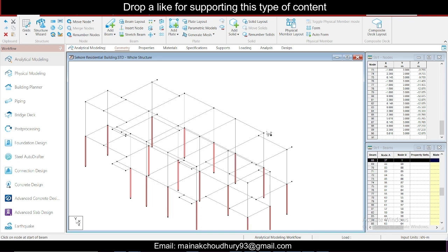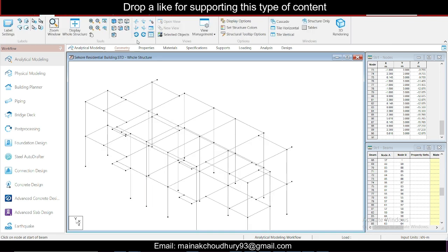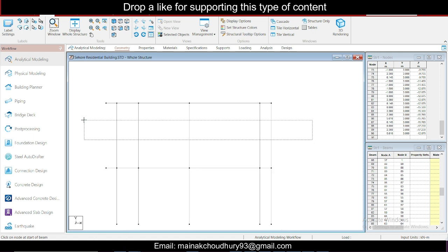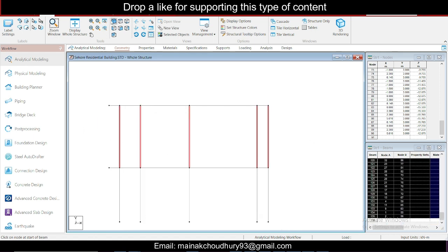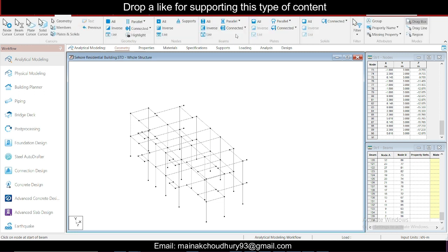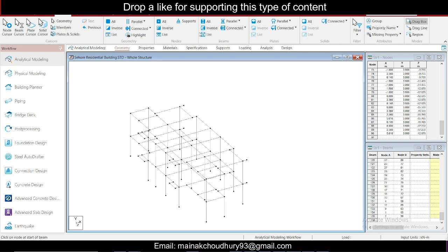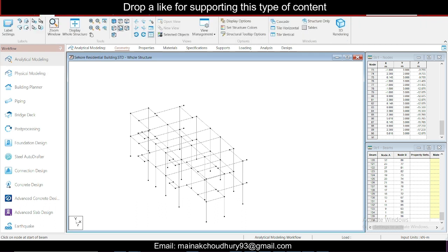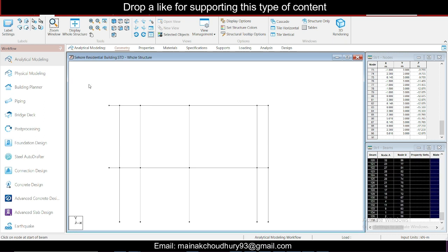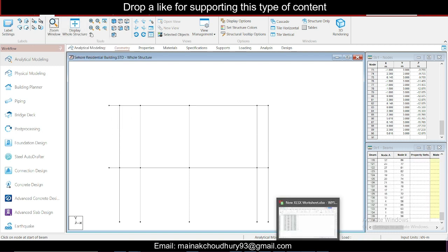So let's check whether there are 18 there. On the isometric we can also check, like select parallel to Y. So there are no half things, all are full, so it is okay. Now since it's okay, we'll go to view, front view, and select this, and let me apply the slabs here also.